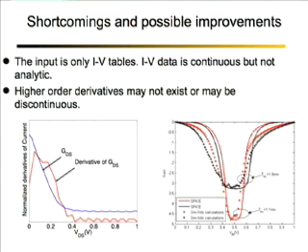On the x-axis, I have VDS, and on the y-axis, I have the normalized derivatives of current. And we see that the GDS here has some ripples as well as the derivative of GDS, which has a huge amount of ripple. So essentially, all the computation that we do, which involves derivatives of current, would potentially have discontinuities or inaccuracies. This is exactly what we see when we plot, let's say, the gain on the y-axis and the V-in on the x-axis of an inverter.